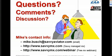There's a second kind of backup alternator that I've seen that is also STC'd for certificated aircraft, and it's an alternator that isn't driven off the engine at all. It actually mounts on the underside, typically on the underside of a wing, although I guess it could probably mount on the underside of a fuselage, and you pull a knob in the cockpit and it drops out a door and is wind driven, and provides a second charging system source in case of a failure of the primary alternator.